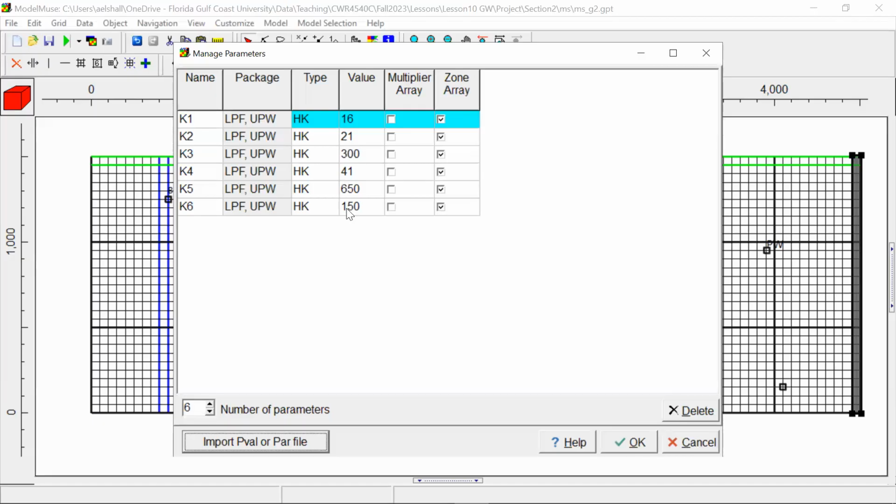And again, as we've seen before, changing these parameters one by one is not only tedious, it is never going to work. If you change the hydraulic conductivity here, it will affect the values in all the rest of your model, not only the head value here. Let's say you fix this one, then you change the hydraulic conductivity here, and this one gets screwed again. So you cannot do this manually. You have to do it automatically.